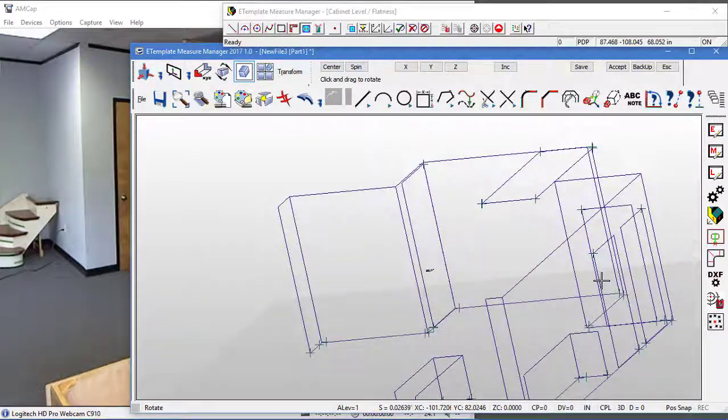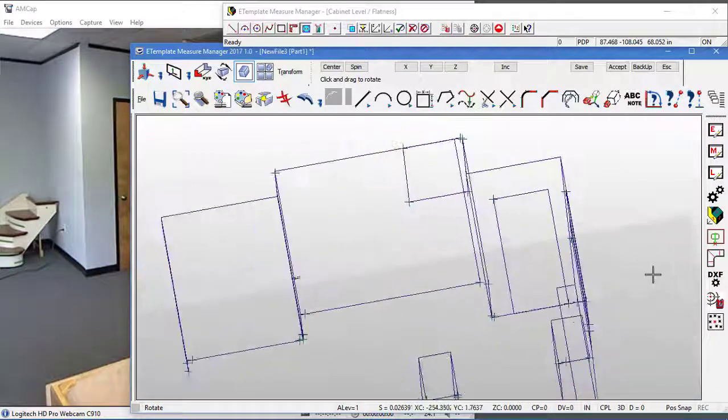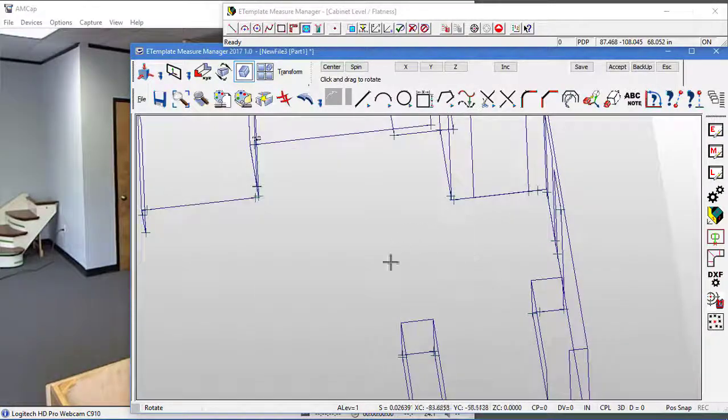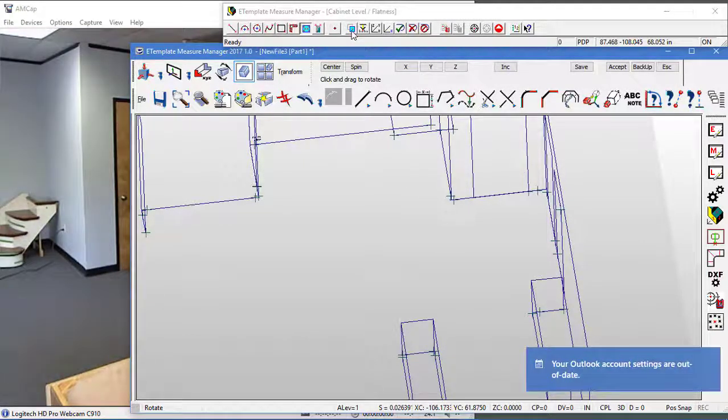And now in the area along here and along here, I'm going to create some patterns so that if he does bring that stairway out and over, or if he just brings it straight down, that where it lands, he'll know how flat the floor is. Yeah, we're in floor flatness mode.